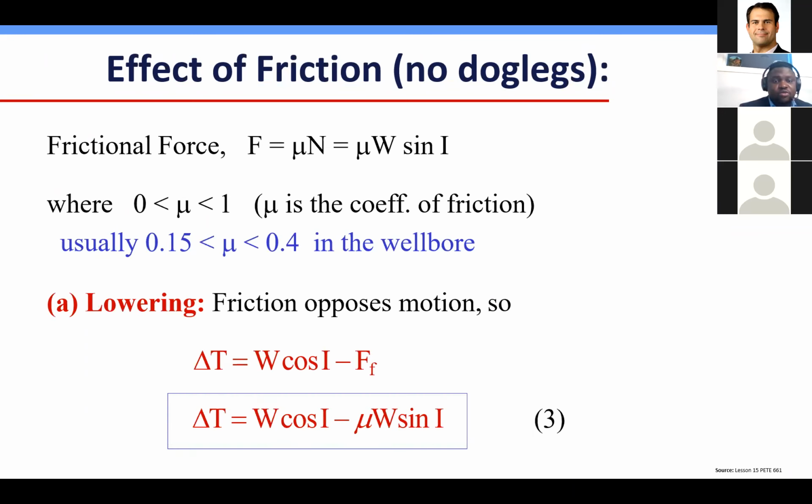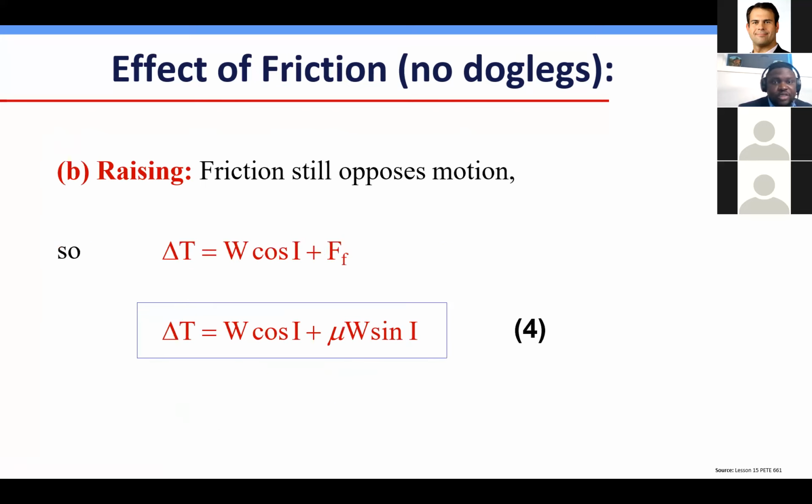And when you're lowering it, the important thing is that for the change in tension, you're going to be subtracting the frictional force when you're lowering. And then if you are raising, you are adding that frictional force in order to calculate the change in tension.